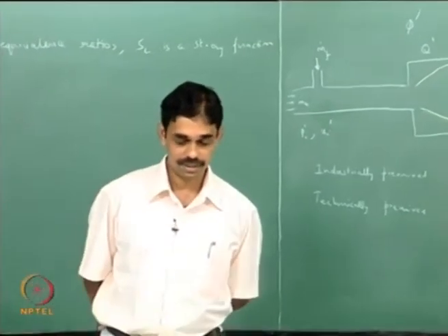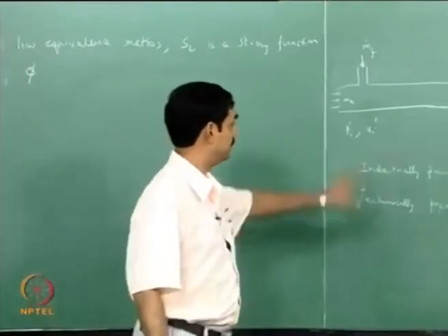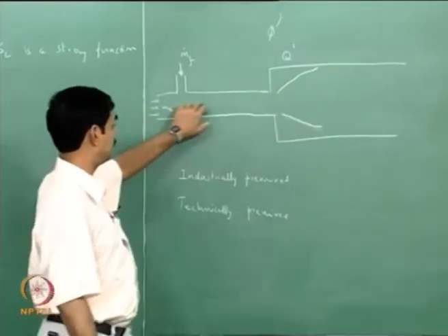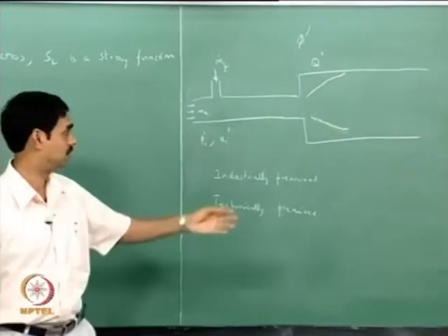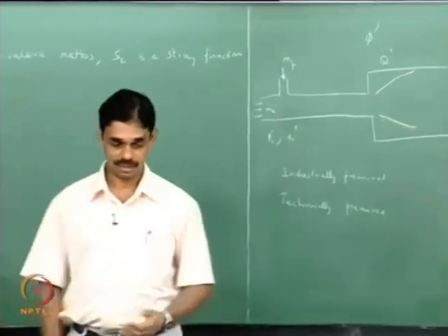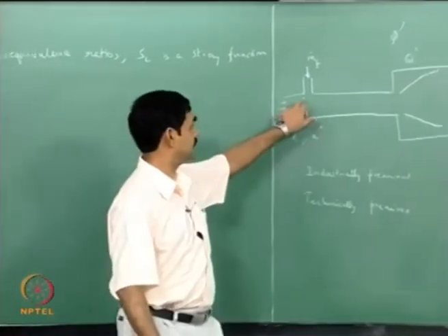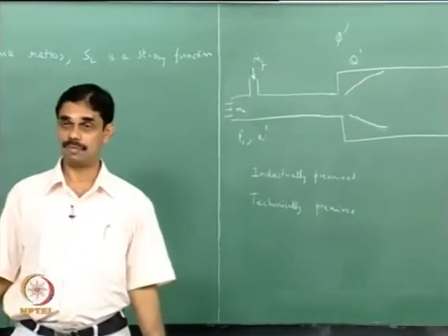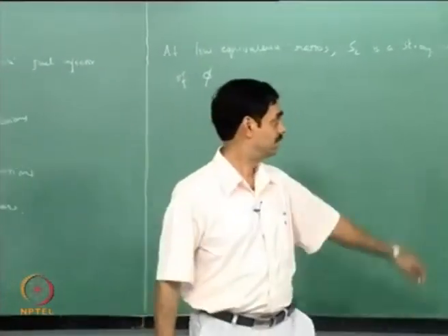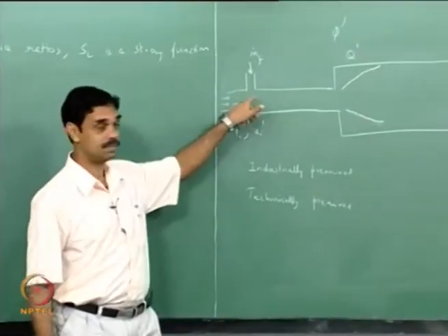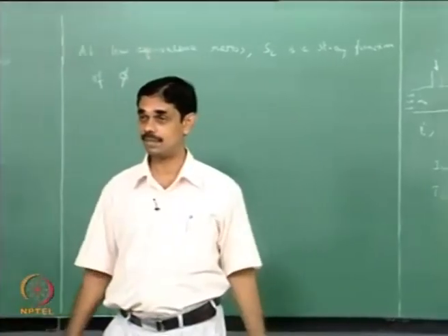So the fluctuations in equivalence ratio are generated by the acoustic waves. They are here in this combustor, they travel upstream, and they come here. That's what I denote by Pi and Ui. So some of the waves come here and then they modulate the fuel and air. How does it physically modulate the fuel flow rate? Anviksha already answered it. Can you repeat the answer again, Anviksha? Is it the velocity or the pressure which modulates the fuel flow rate? Why does it do it? Sometimes it will make more fuel flow, sometimes it won't. When is more fuel coming and when is less fuel coming?